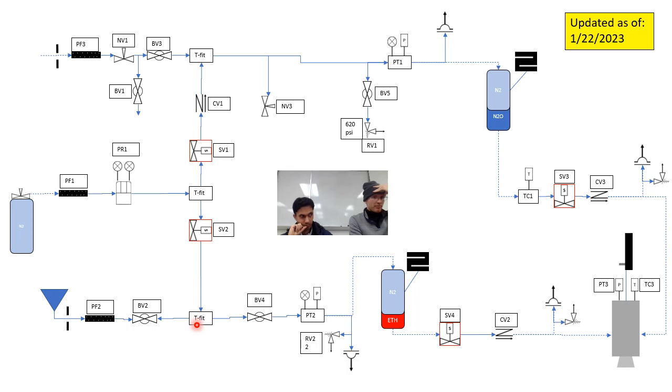So your pre-fill process begins with, we'll probably have a lot more details on this in the future, but effectively it's going to be a series of checklists where you're testing each instrument and each solenoid when everything is vented open to atmosphere, just to see if we can turn everything on and everything's working nominally. That's important because we don't want to fill this whole system up and then realize that one of our solenoid valves is not operating properly. So we'd like to test that before we fill with anything.